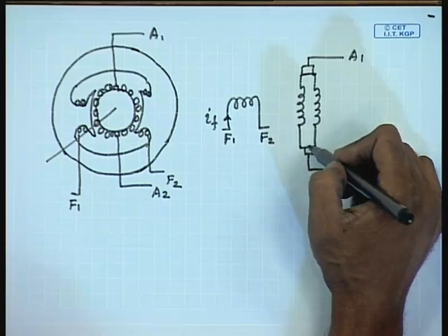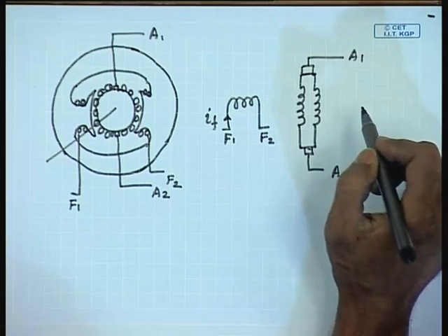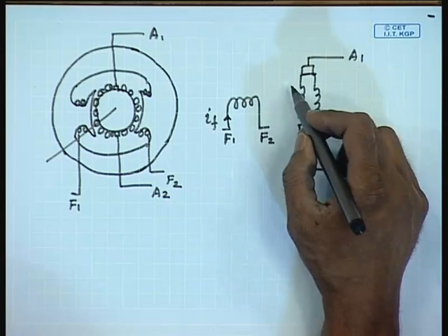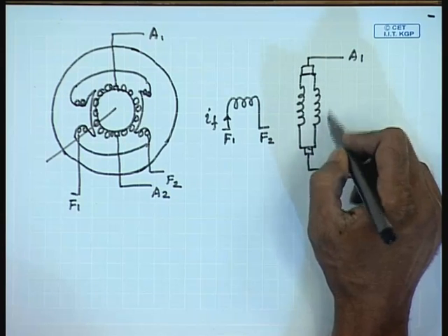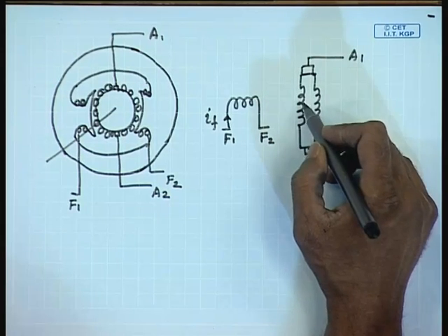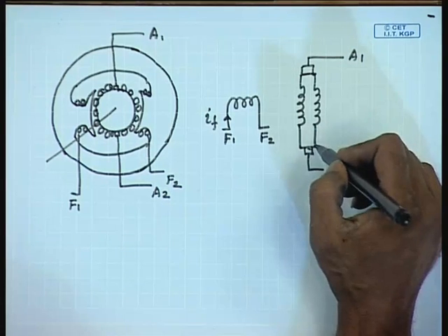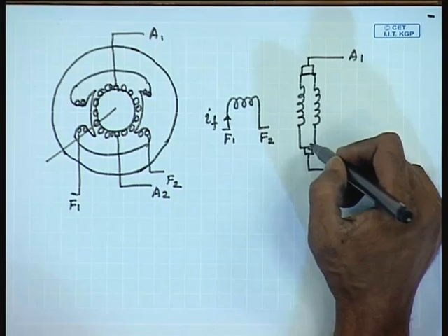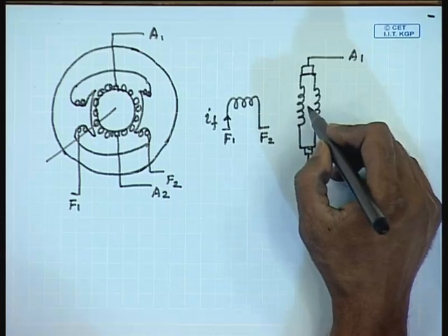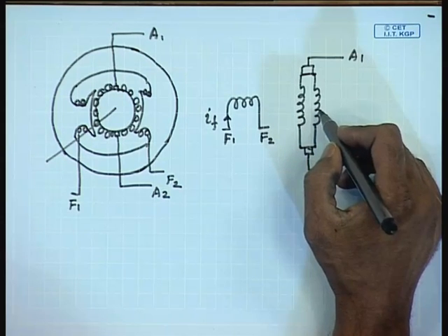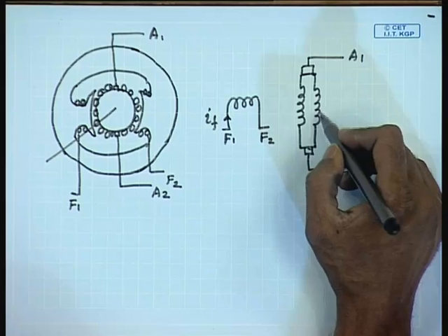Therefore, it is reasonable to represent the armature of a DC machine by a parallel connection of several coils. The individual constituent coils may change, but the number of coils between two brushes remains always constant, the number of parallel paths being equal to the number of poles for a lap connected machine and equal to 2 for a wave machine.